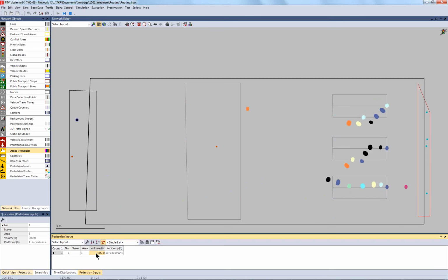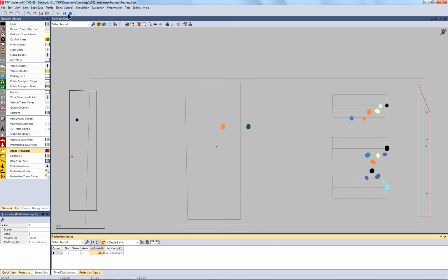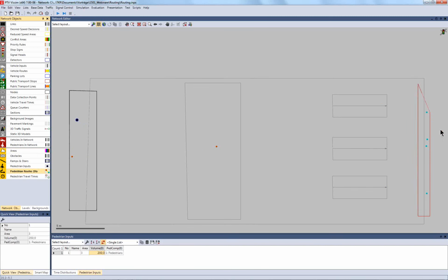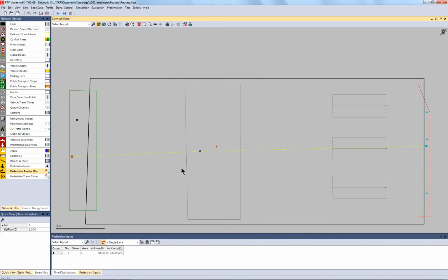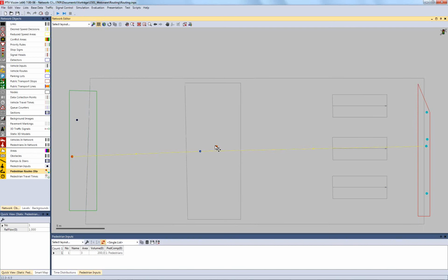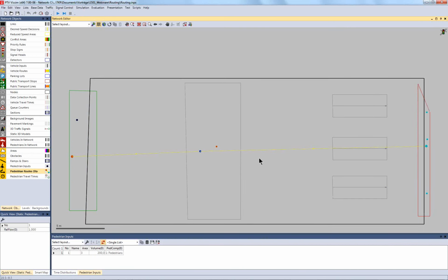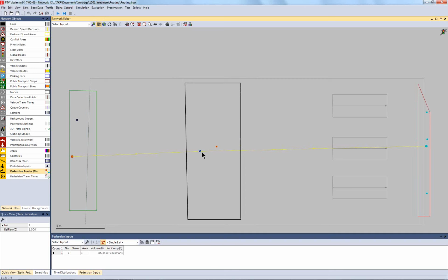This type of partial routes, the service desk partial routes, they have one special property which is different from other partial routes. Before I told you that whenever a pedestrian steps on an area where there is a partial route decision, where the routes lead back to the main route, the partial route decision applies, and there doesn't need to be an intermediate destination of the main route on the area where there is the route decision of the partial route.